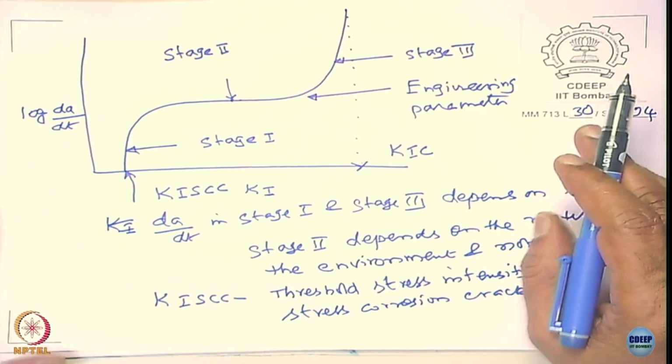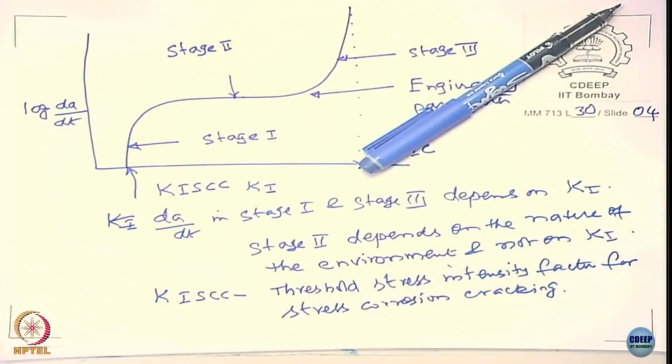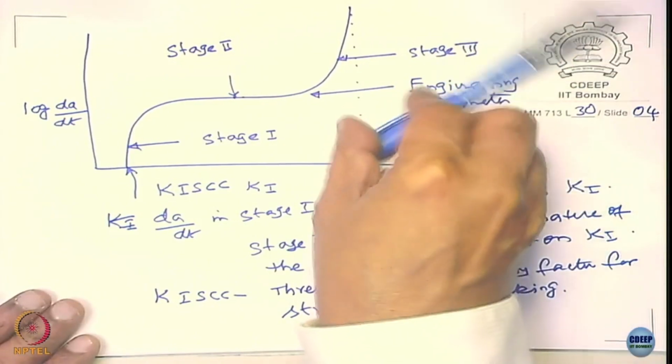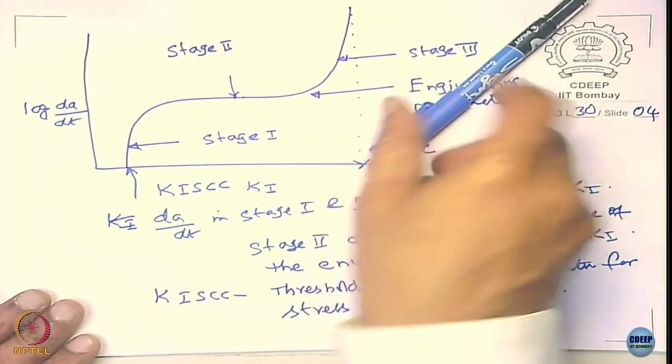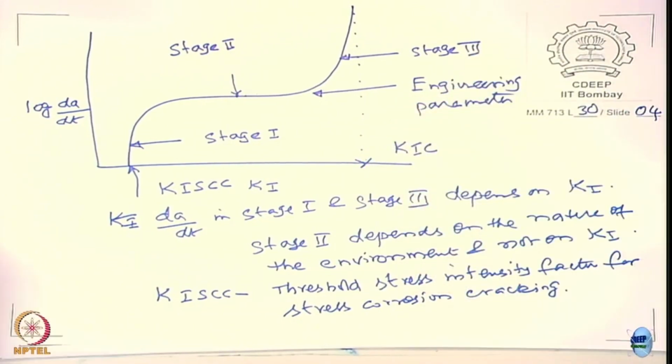Above K1C only will the crack start growing. The crack is there, but it does not grow if it is less than K1C, if there is no environment. You will see, it will go like this or like this, depending upon toughness and other things now, but it starts from here only. Yes. Did I answer the question?